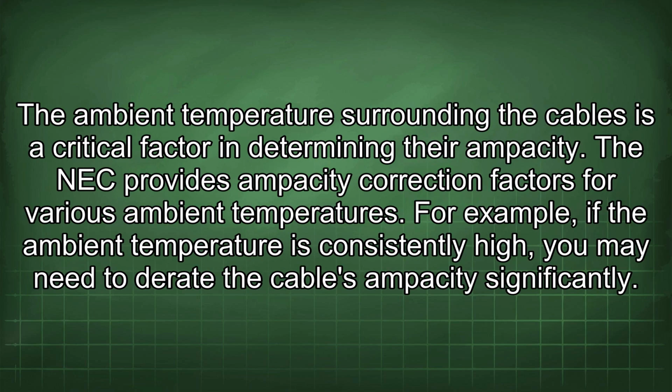The ambient temperature surrounding the cables is a critical factor in determining their ampacity. The NEC provides ampacity correction factors for various ambient temperatures. For example, if the ambient temperature is consistently high, you may need to derate the cable's ampacity significantly.